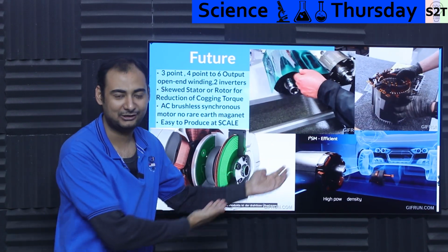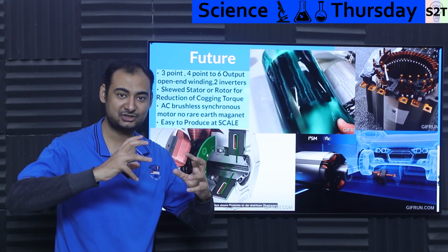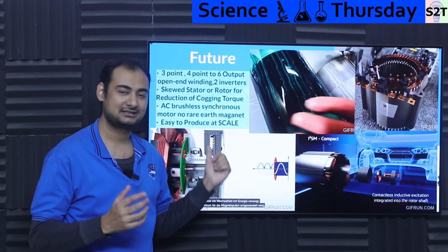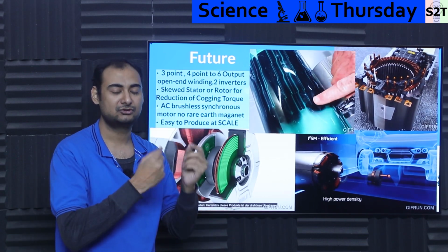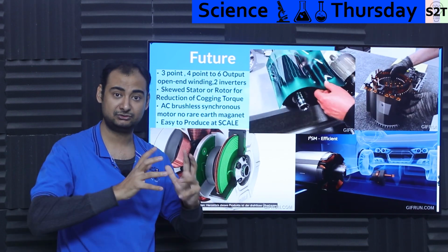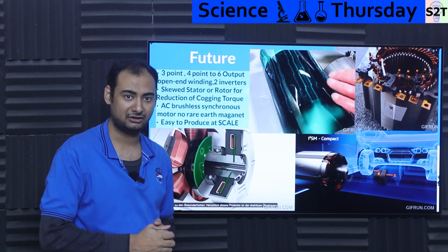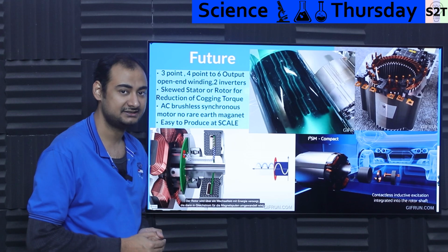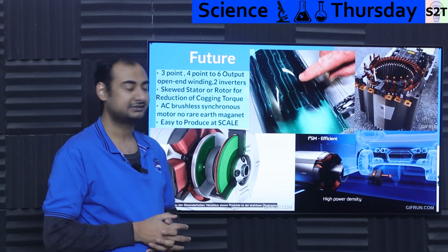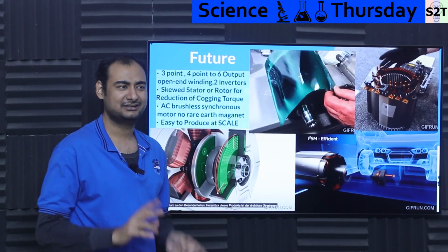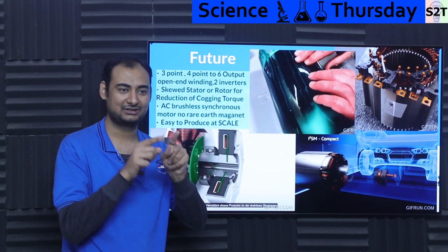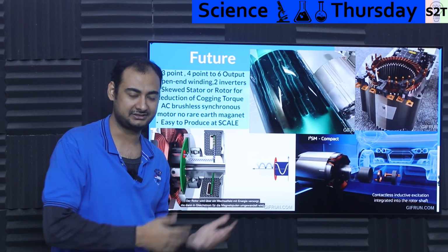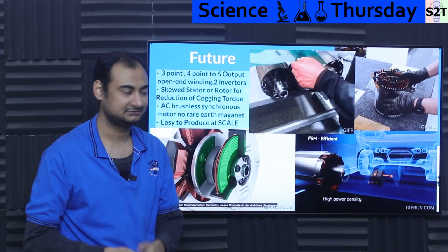Why the heck do you have coil wires in there? And again, if you need that skewing, which again, both of them either don't have skewing or are not showing the skewing, it's like use a copper system, round wire copper for the stator, skew the copper, benefit, high frequency is now unlocked and you can have ultra high DC current with low skin effect losses, high copper fill, so the rotor can be lighter. Like it just feels weird, it just feels inverted. It's like you should have hairpin in the rotor, not in the stator. Stator loves AC, give it AC. Rotor loves DC, give it DC.